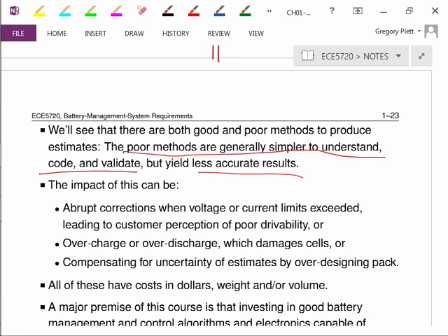So suppose you do something else. You say, okay, you can have 30 kilowatts, and the guy pulls out to pass the semi-truck, and you realize, oh, I made a mistake. I said you could have 30 kilowatts. I was wrong, but I don't want to just cut off power because that's a safety concern. Instead, I'll honor my prediction, even though I was wrong. I'm going to let you take 30 kilowatts out of this battery pack, which probably can happen. You can probably still do it, but we're going to either overcharge or over-discharge cells. If I'm accelerating, I'm going to over-discharge cells, and that's going to cause damage.